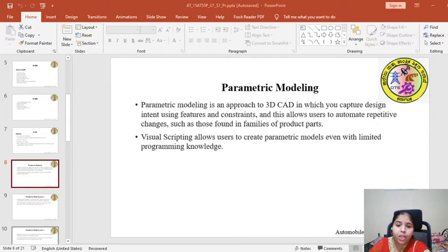See, parametric modeling is used to create models of parts separately and then you can assemble them. It is so easy that once the assembly is done, if you find any mistake in the drawing, dimensioning or some feature, you can just go back to that particular sketch and edit only that dimension or the feature and return back to the assembly. Once you have already done the assembly model, now you find that the assembly is not fitting due to some problem, some constraint you might feel.